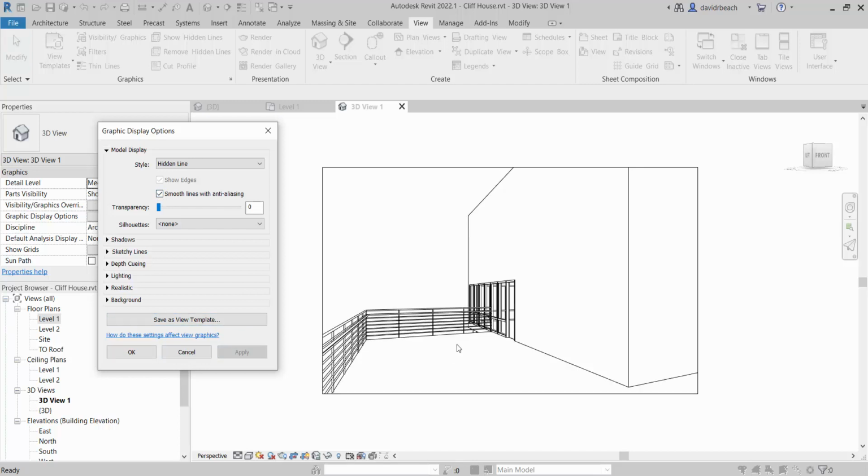Essentially, anti-aliasing is going to add more gray. It's going to give you more detail for the lines. It's asking more of your graphic processing unit, your GPU, but not that much more. So really that should just be on by default. Anytime I see work that's on the wall and I see funky lines, it's either a problem with resolution or somebody forgot to click that button. Always turn it on.